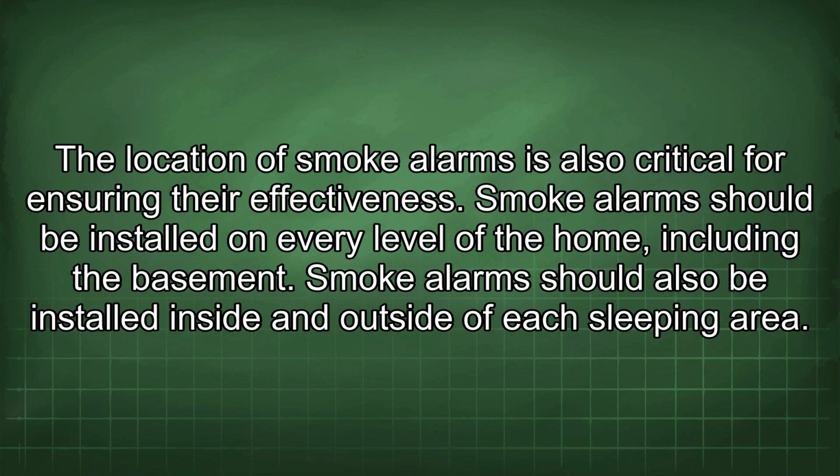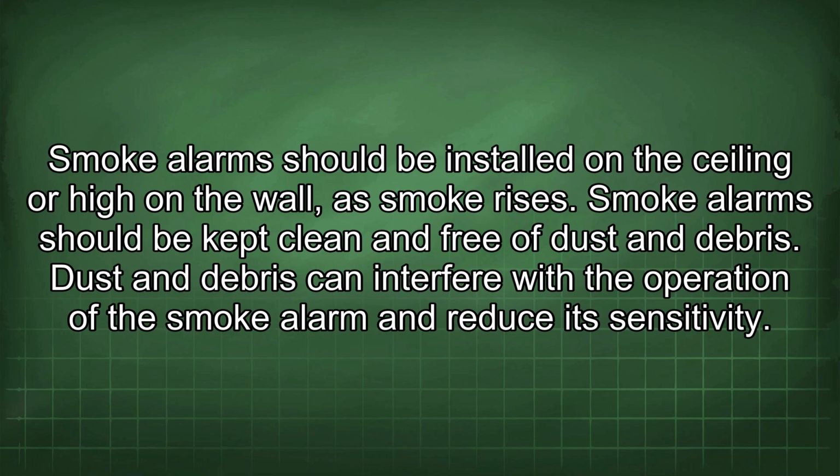The location of smoke alarms is also critical for ensuring their effectiveness. Smoke alarms should be installed on every level of the home, including the basement. Smoke alarms should also be installed inside and outside of each sleeping area. Smoke alarms should be installed on the ceiling or high on the wall as smoke rises. Smoke alarms should be kept clean and free of dust and debris. Dust and debris can interfere with the operation of the smoke alarm and reduce its sensitivity.